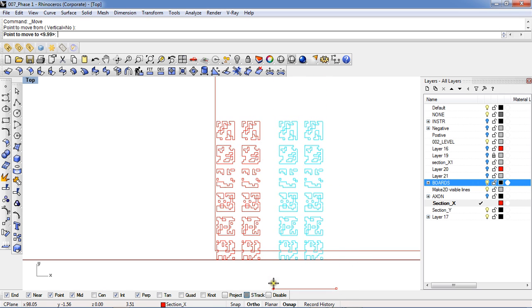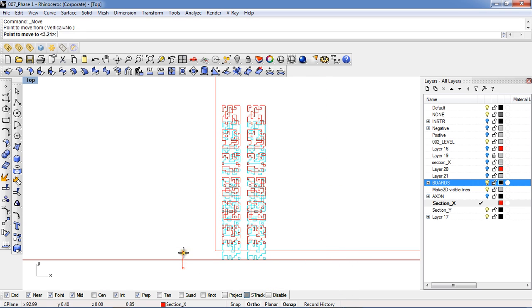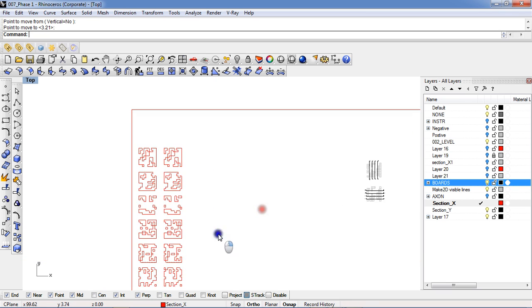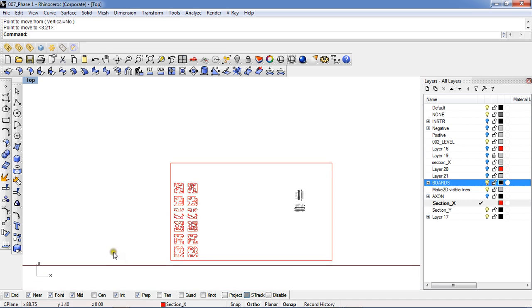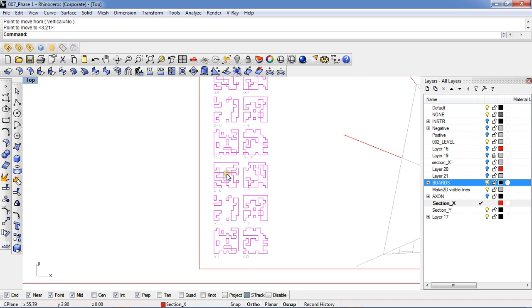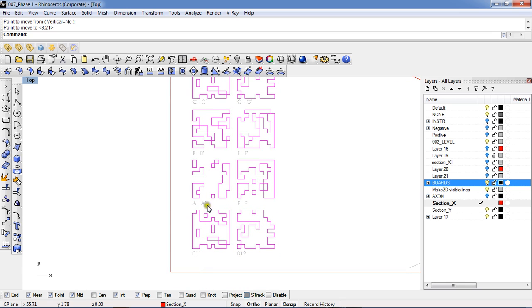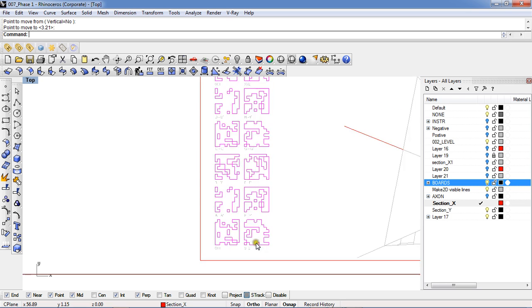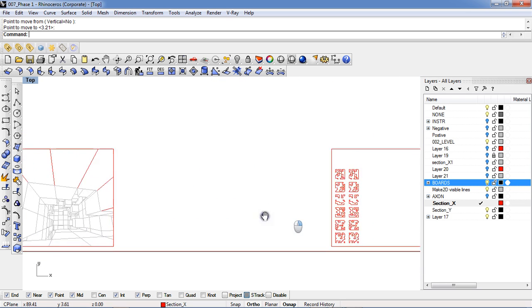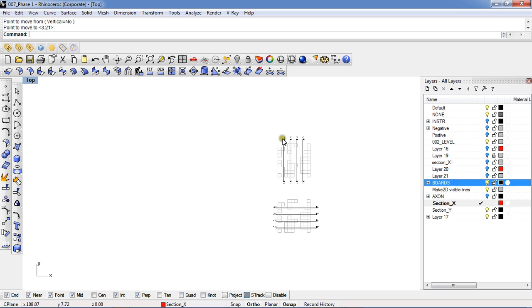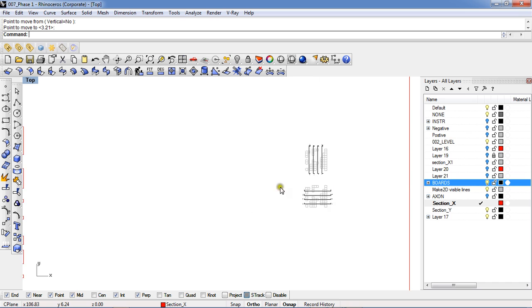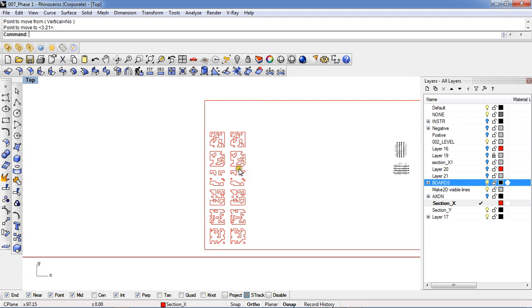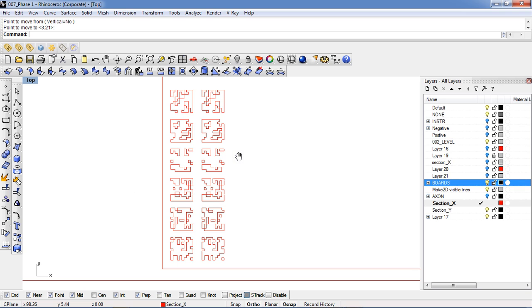Move them into position like that, and there's your first set, or second set, first and second. You need to go in and properly label them. Maybe the left is the X direction and the Y will be the right column. Then you need to continue and create a plan showing the X and the Y directional, showing the sections in which they're being cut through the model. This is a good way to indicate how your sections are being directed.